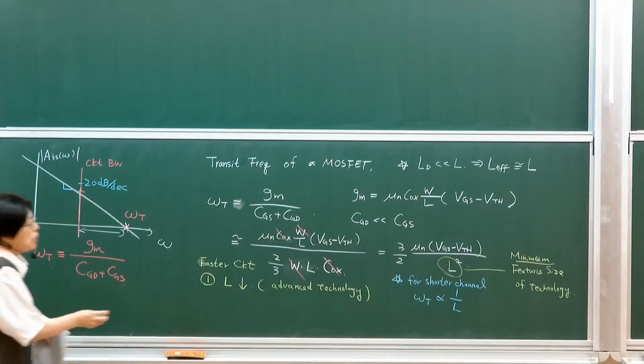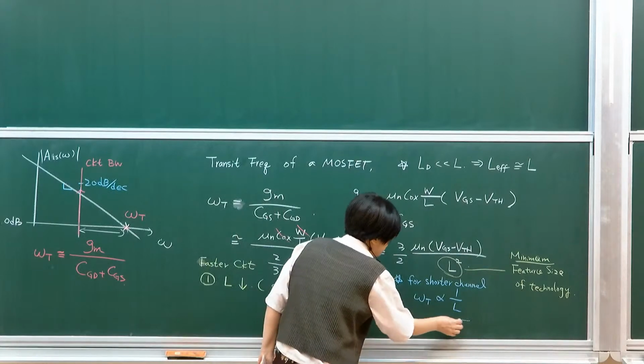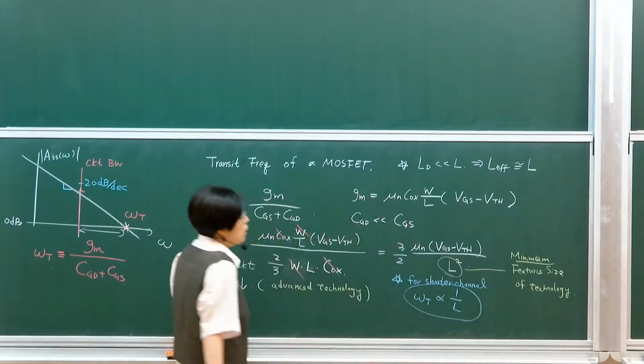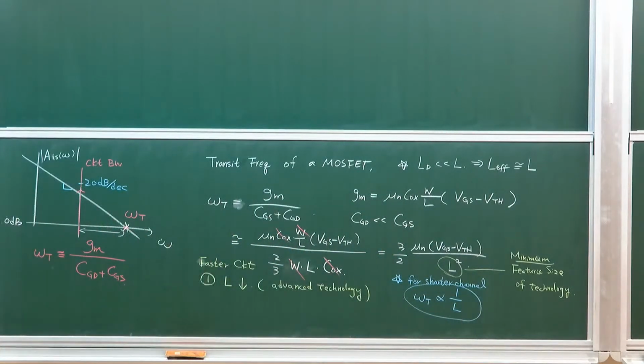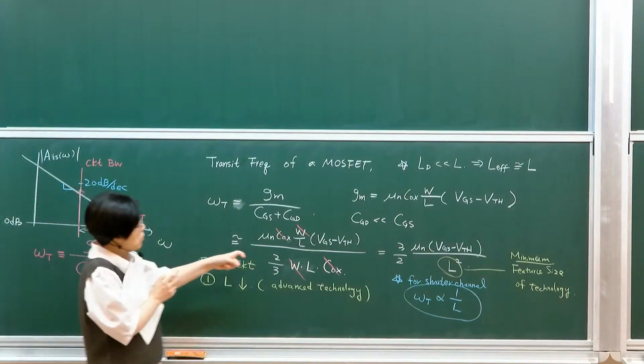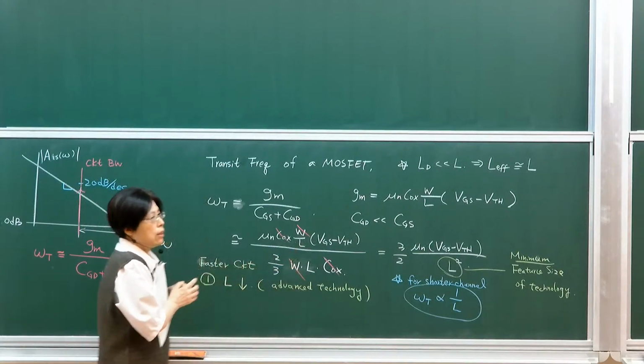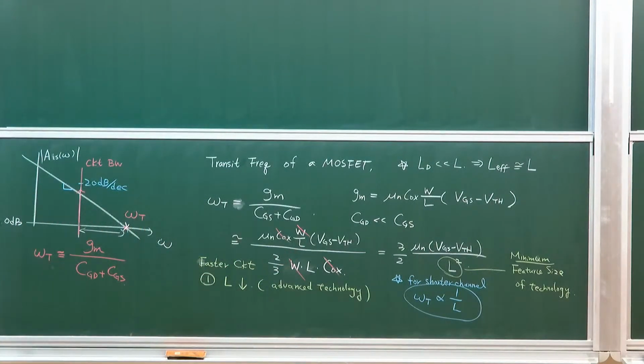The main reason is because of this. For shorter channels, you get a frequency dependency less aggressively. This is because of some non-ideal effects. If you take courses in solid-state circuits, you get a sense as to what happened. These models will no longer hold in shorter channel devices.